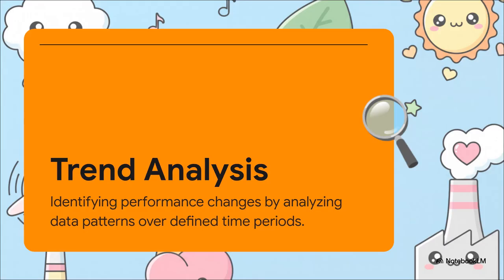To actually get those insights, we rely heavily on trend analysis. Basically, it's about identifying gradual deterioration or improvement by looking at data patterns over defined time periods. And it is absolutely vital. If you're tracking water consumption, trend analysis allows you to spot seasonal variations or subtle equipment inefficiencies, like, say, a slow leak in a cooling system, long before they escalate into costly emergencies or absolute compliance nightmares.